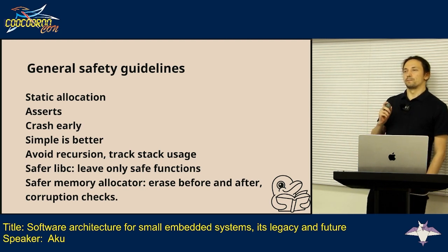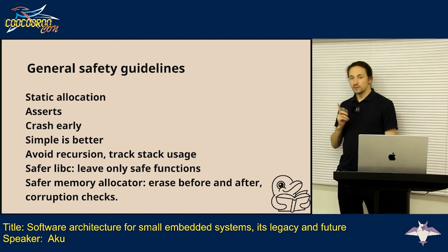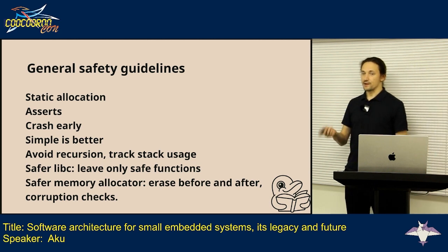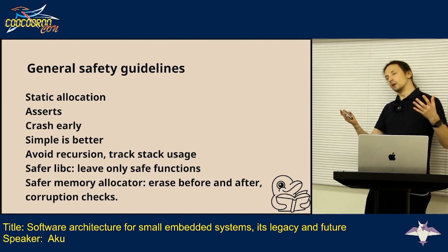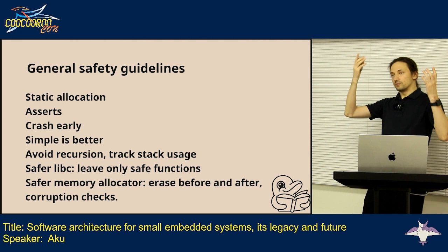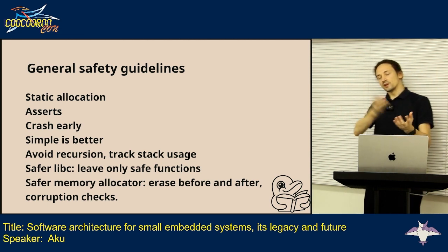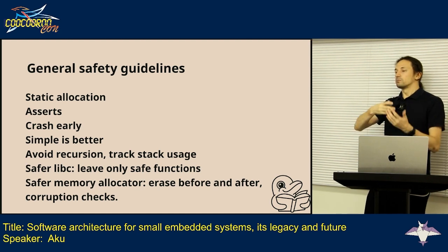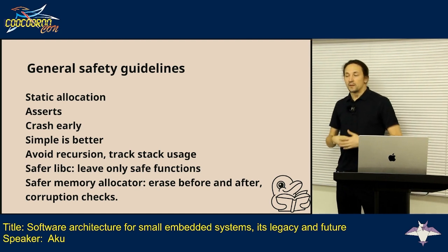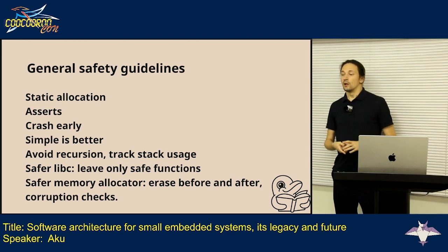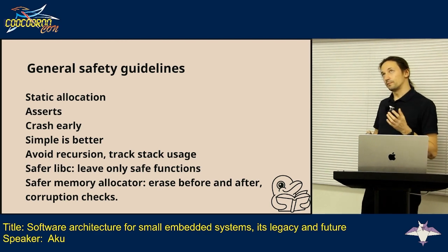Especially it's important because in big systems with an MMU, you actually can rearrange your physical space on the fly. You can just map blocks and then, transparently for your application, on the kernel level, you can copy data from one block in physical memory to another and then just change the mapping. So for the program that's running in user space, there will be no changes. But for the kernel, you will be able to defragment your memory space. That's not the case with microcontrollers because we don't have a memory management unit.